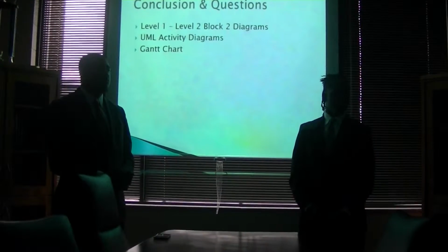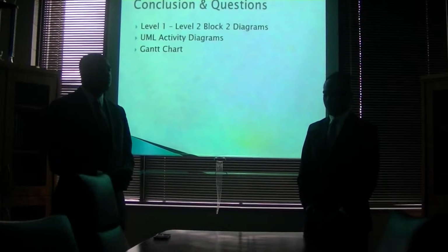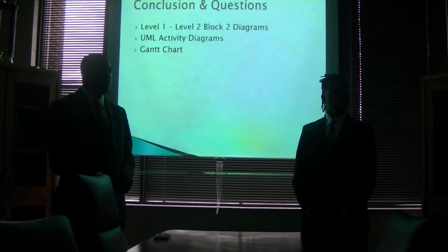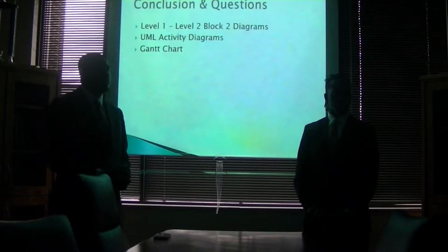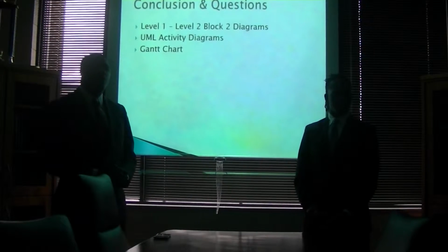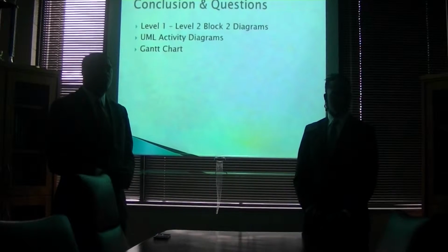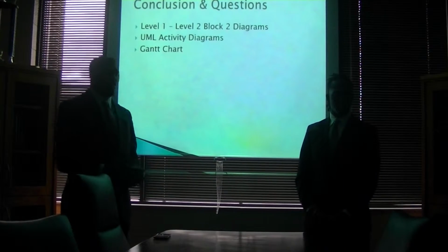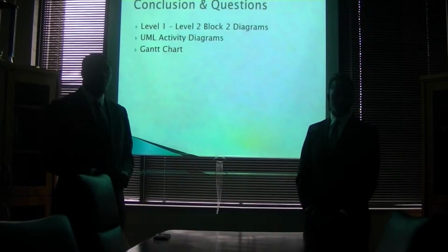Sense the voltage level of the tablet, and if it's reaching the threshold and there's not enough, then it has to automatically hook in the battery source. Yes, sir. So this is all automatic. This will prevent overcharge on the tablet. It also increases the life of the battery in the tablet, because too much power on the battery will kill it.